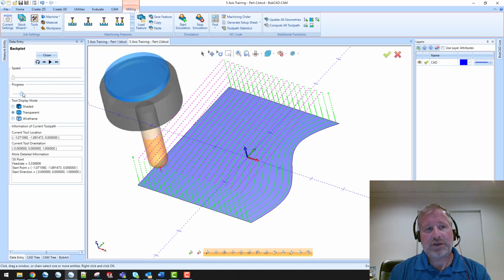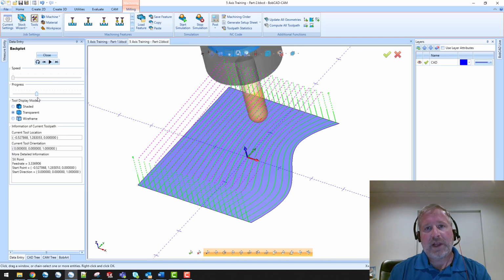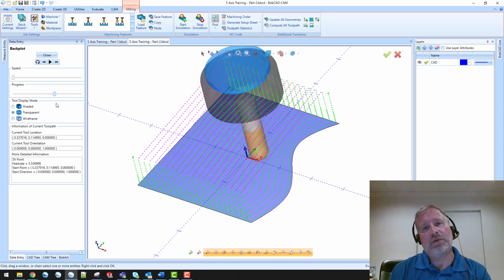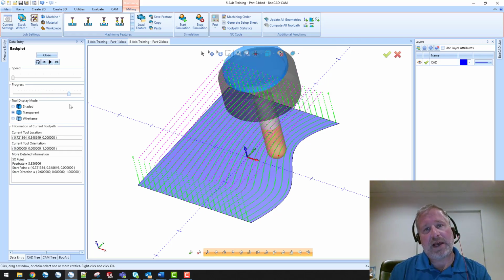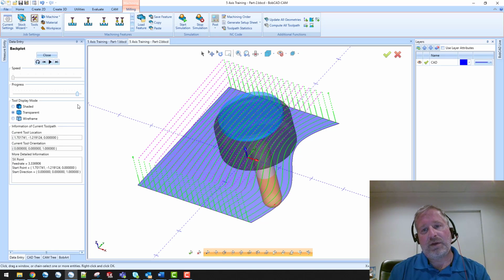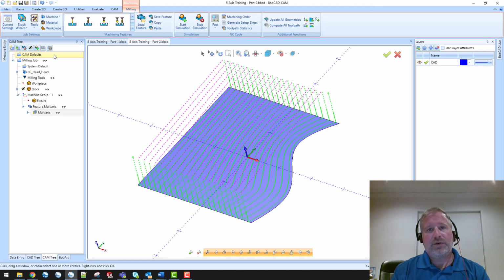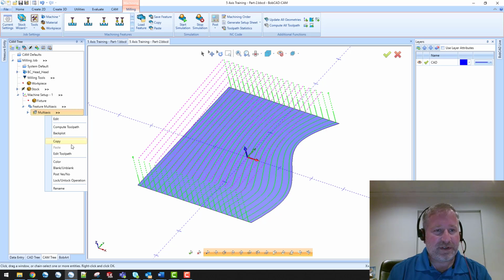surface-based 5-axis tool path gives us a tool path where the tool is going straight across the part, and then as it gets over to that other edge, it starts blending into that profile so that the last pass is following the profile of that edge. Now, what is that going to do to our tool tilting strategy? Let's take a look and see what happens.